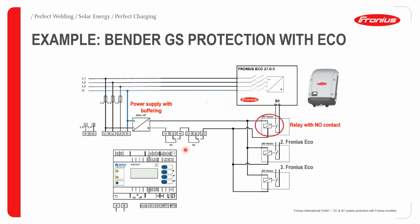And then since we're using both contacts, that is K1 and K2, they are looped together via terminals 14 and 21, which is the normally open contact for K1 and the common point for K2, as you can see in this case. And then the connection is completed onto the relay by terminal 24, which happens to be the normally open contact for K2.